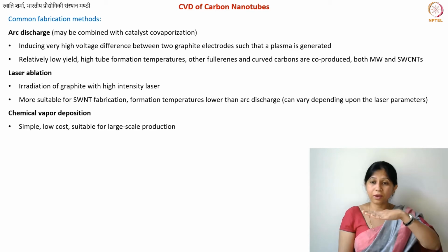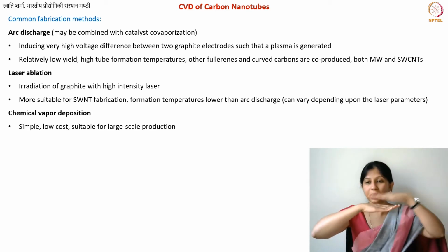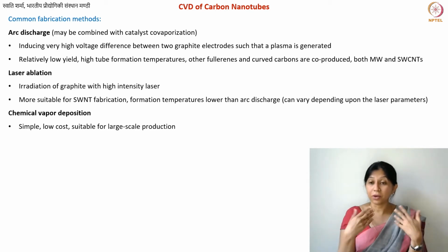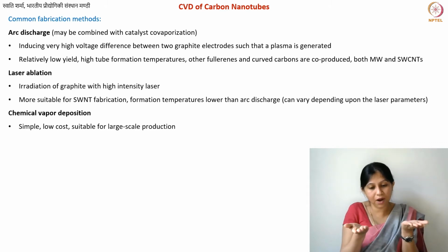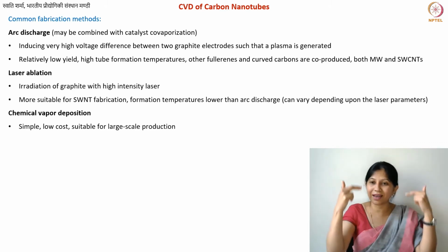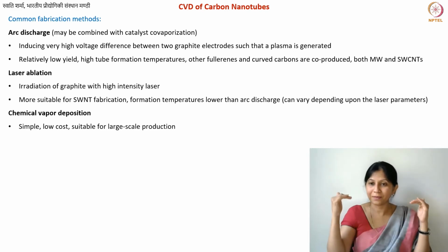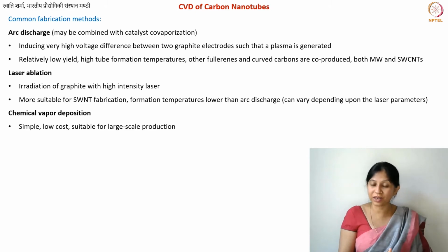You get one film, on top of that you get another film, and then another film. So it is indeed difficult to stop the process at one single film. This means that the second layer of carbon also serves as a catalyst for the third layer, the third layer serves as a catalyst for the fourth layer. So carbon can deposit on top of carbon. In fact, in the case of pyrolytic graphite production, we are using graphite itself as substrate, you know that, okay?